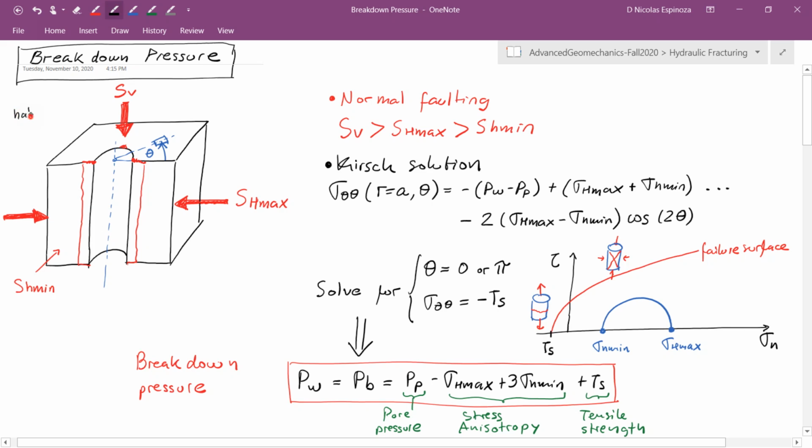At least that's what I have drawn in here. But try to think about the entire wellbore with the full domain. In this model, if we have in situ stresses and a pressure inside the wellbore, we could find instances of shear and tensile failure around the wellbore, depending on the orientation of the wellbore and depending on the orientation of the stresses with respect to the wellbore.